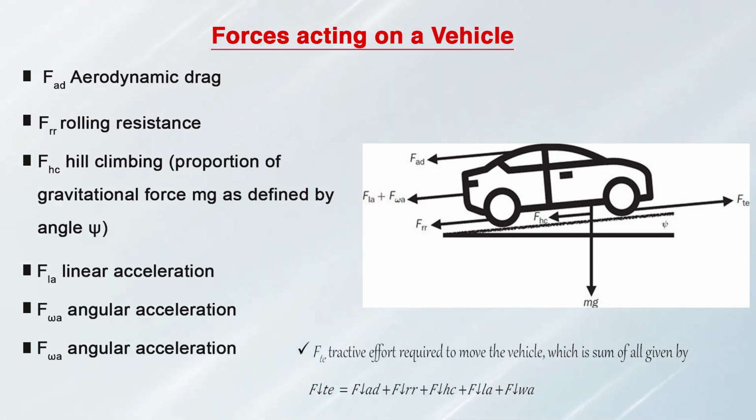That is the constant velocity: when the vehicle is going with constant velocity, there is a force that is required to be overcome by the vehicle. All this put together we called the tractive force. So, this tractive force is the sum of all the forces individually. The major aim of understanding all the forces is to evaluate the power. So, we have then discussed how to evaluate the power. The power is nothing but force into velocity. All these expressions have been given, and the power expression finally also has been given.